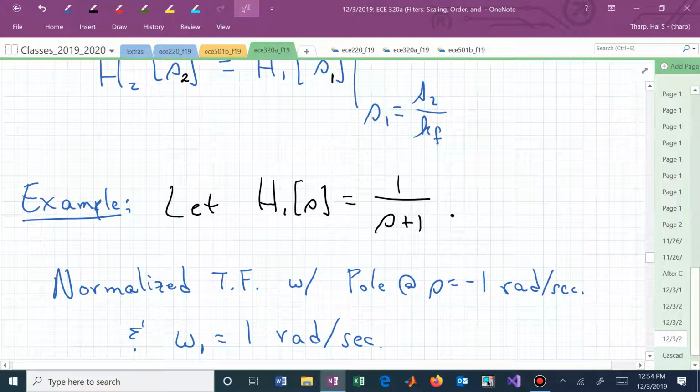One answer? I said there could be 2. No, 1 is okay. That's the absolute DC. You could also have told me it in dB. You could say, oh, the gain is 0 dB. That would be another for that particular transfer function.